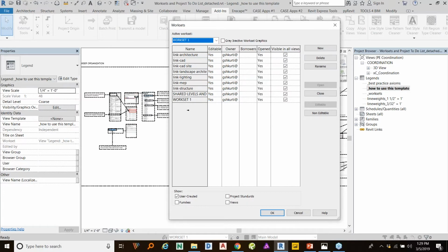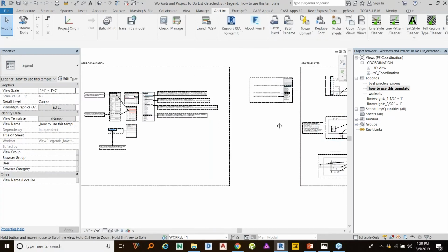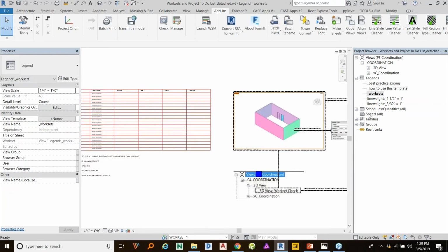And what that means is that all uppercase work sets live inside of the live model, whereas all the lowercase work sets are linked in. And this is already giving you a head start, so you know how to continue. But to further drive the point home, what you can do is create a legend which says, all right, this is how work sets work.